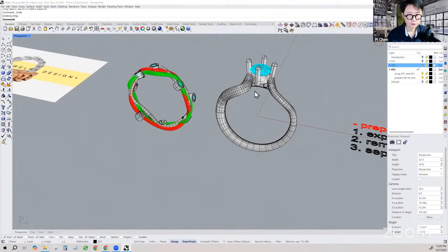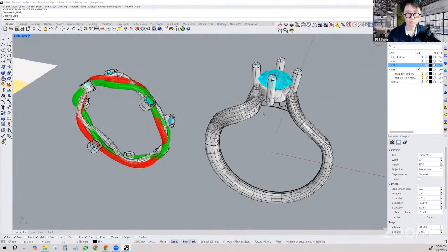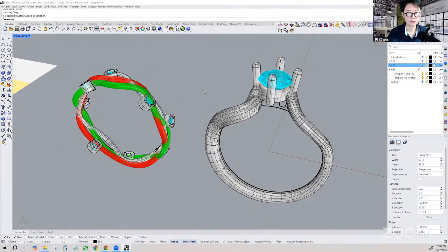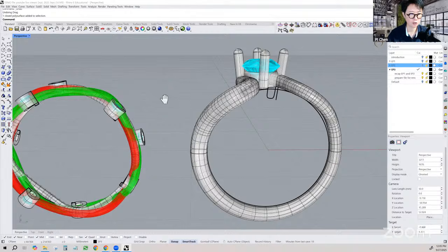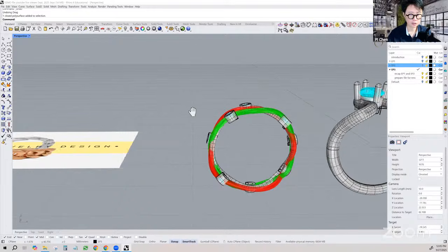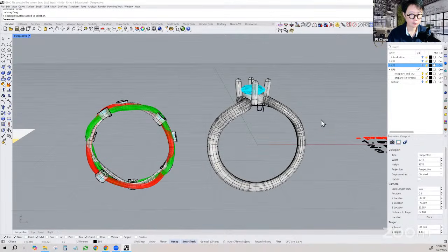But one of the things I wanted to reinforce a little bit is that the model we are making right here is called a production model. It's not for rendering, so you're going to see the prong is super long, and the bezel is higher. The reason is we need to weigh how much metal we need to clip off on the bench and bend the prong, and how the jewelers actually work on that. I do have a playlist for stone setting showing you what happens physically on the bench. For you bench jewelers, you probably know what I'm talking about.